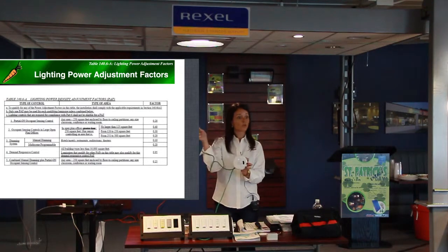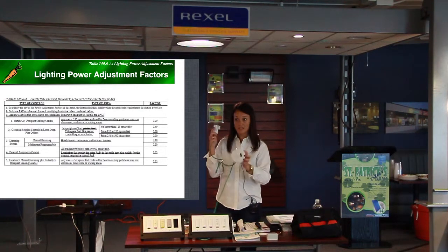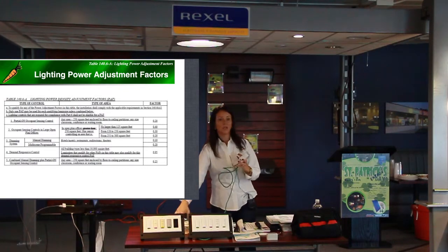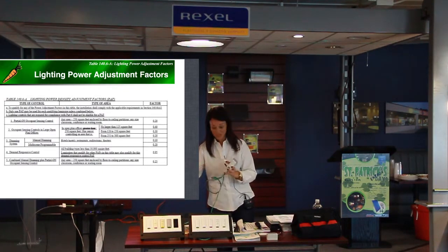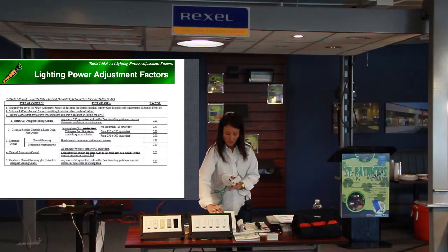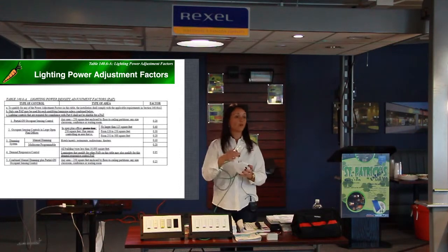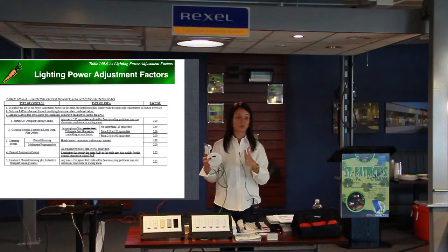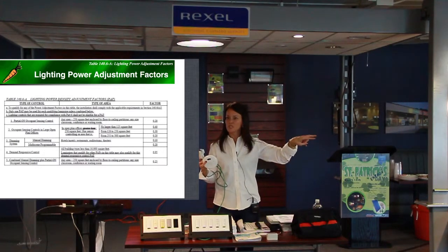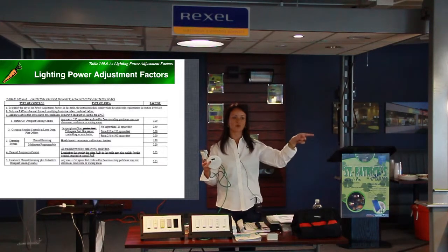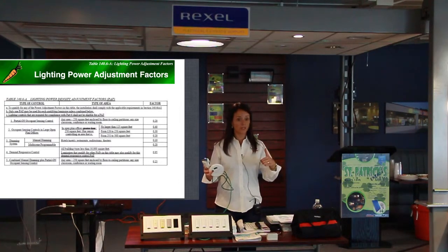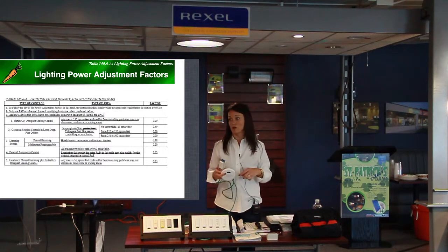So if the contractor is working in 100 rooms in the space and they all have an occupancy sensor, a 2-button switch, and A/B switching in that space, or even dimming. So there's a larger room controller that can do dimming for all the dimming requirement areas. Out of the box, we would only turn on half of the lights. That's how WattStopper works. If you're using a wall switch sensor that has 2 relays, you have seen that before, an occupancy sensor that has 2 relays. The way that the dip switches are configured is half of the lights turn on automatically, the other half you have to manually turn on.